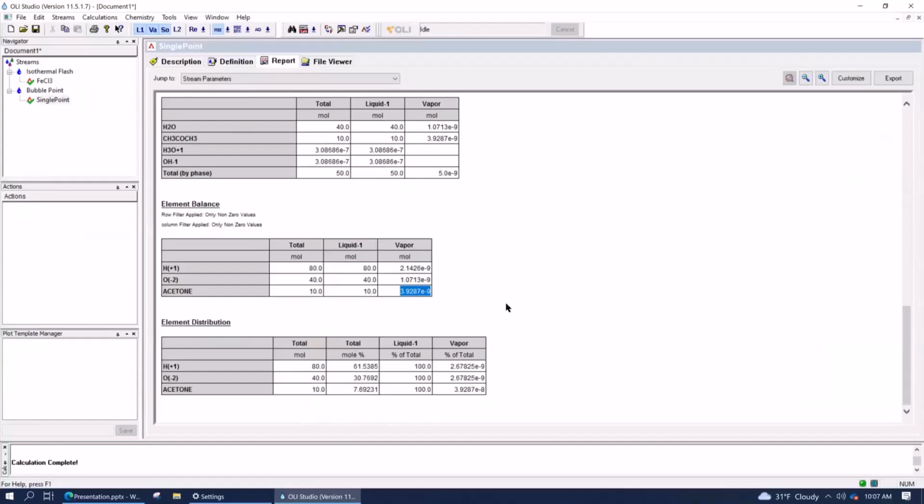Okay. The other way of answering your question is mass transfer limitations. Is that the system, even though it evaporates, there's mass transfer limits, because CO2 is a perfect example. It's like the poster child of poor mass transfer. Your system may be at steady state, but you may be far from equilibrium with respect to CO2. And under those cases, this tool isn't the right tool to predict, let's say, mass transfer limits. We'd want to use some sort of process simulator tool for that. Okay, I guess more to discuss there. Yeah. Thank you. You bet.